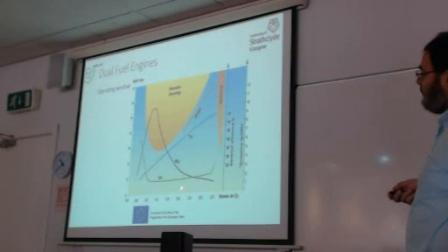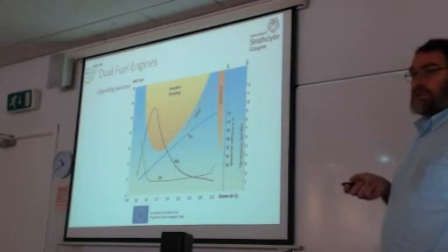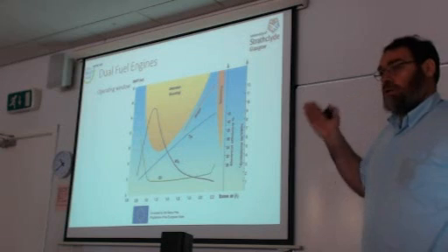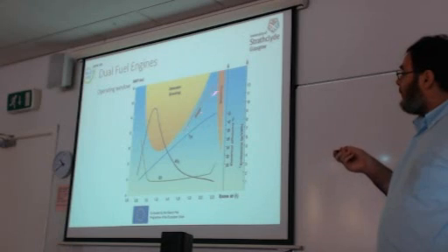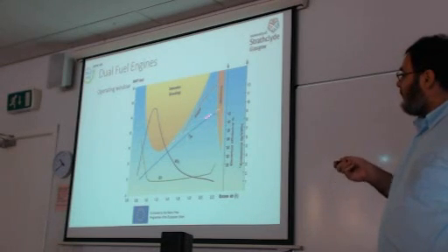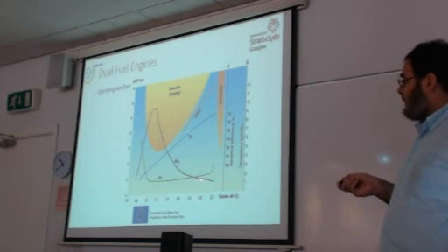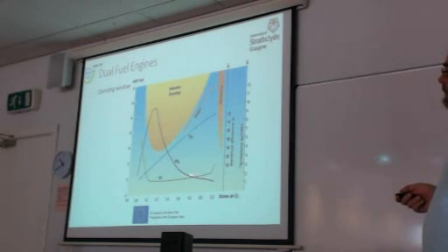And if we see the lambda values, as I mentioned, at full load the window is very small, from 2 to 2.2. But in lower loads, you can see that the window is a little bit larger, from 1.8 to 2.2. So we need to remember that the premixed combustion engines, which means all the 4-stroke dual fuel engines and the 2-stroke Wärtsilä engine, can operate in this lambda window. And this is the curve of BMEP. This is the efficiency of the engine.